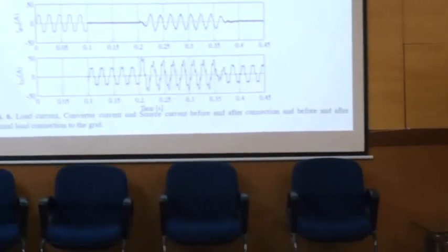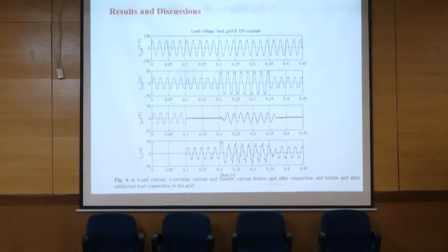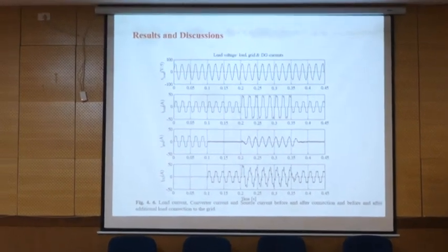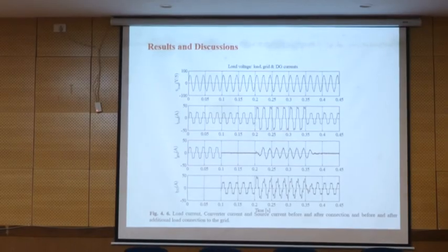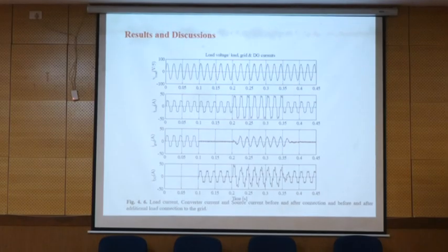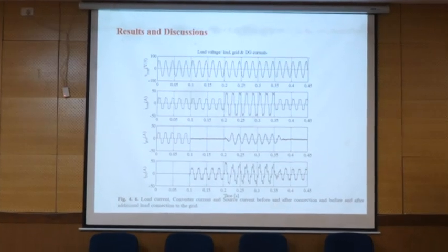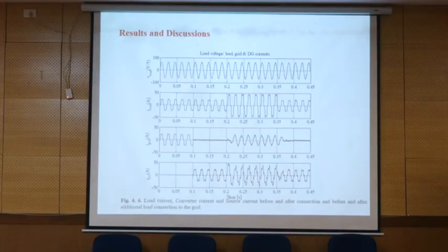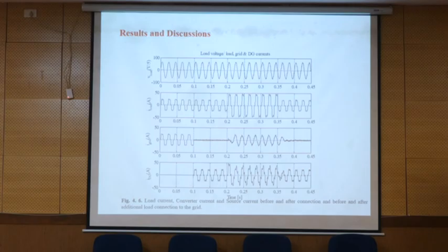The reason is that the maximum power we provide by converter is less than the power that we need for the load. So for this reason, the generated power is not enough to compensate all the load. So the rest of the power, which is fundamental frequency active power, is compensated by grid. So it doesn't provide any problem for the grid. You just pay for the normal bill.